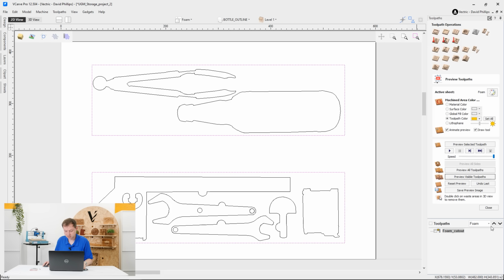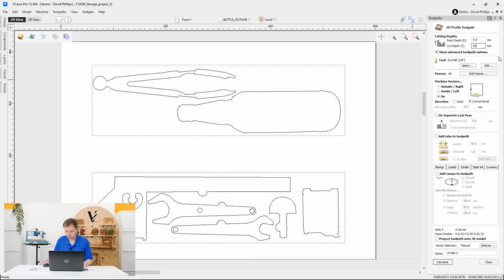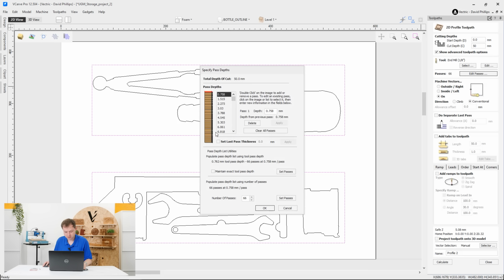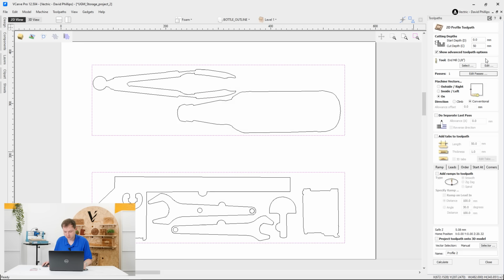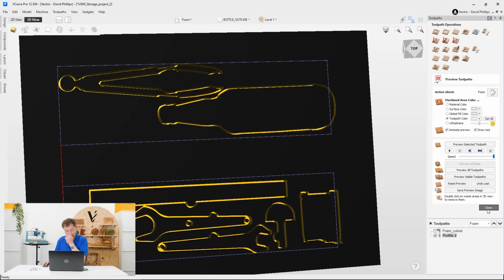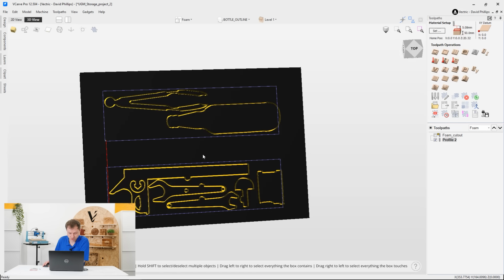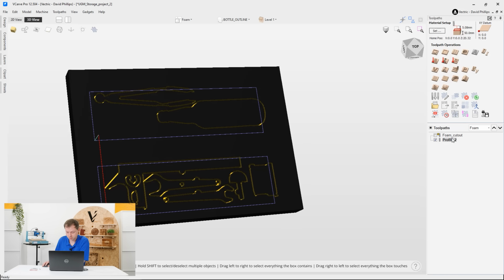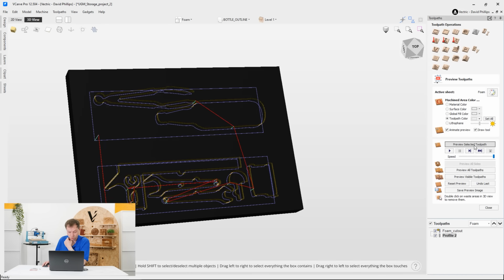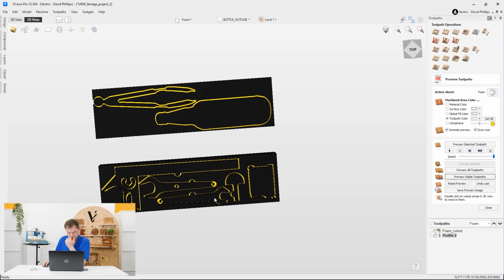Last thing to do here really is to set up the cutout profile. This is very simple, just a full thickness, single pass with this longer 1/8 inch end mill that I'm using. They do supply specialist foam cutting tools which are additionally sharp for use with foam cutting. So that's one thing to bear in mind, and I'd recommend speaking to your chosen tool manufacturer for the recommended tools and feeds and speeds for your particular setup. And there we go, those are our 2 options.